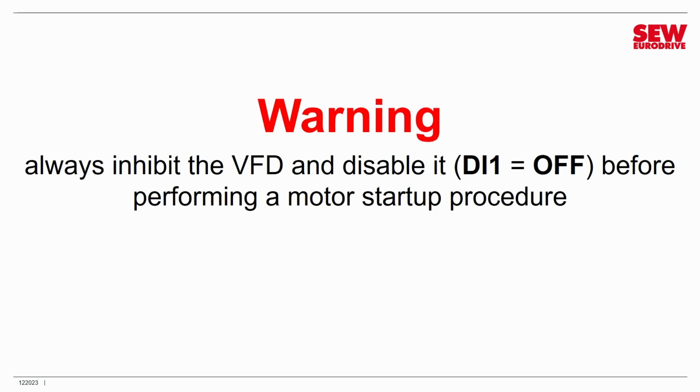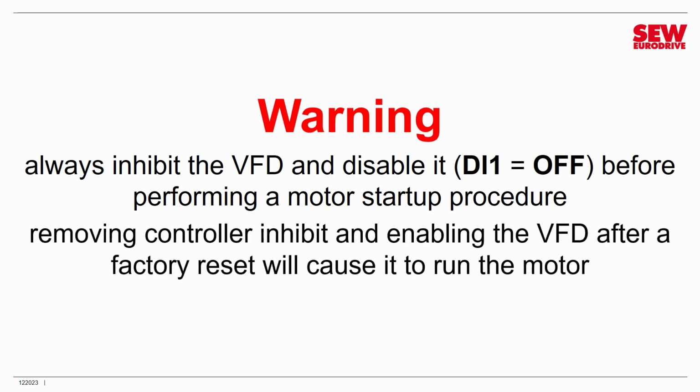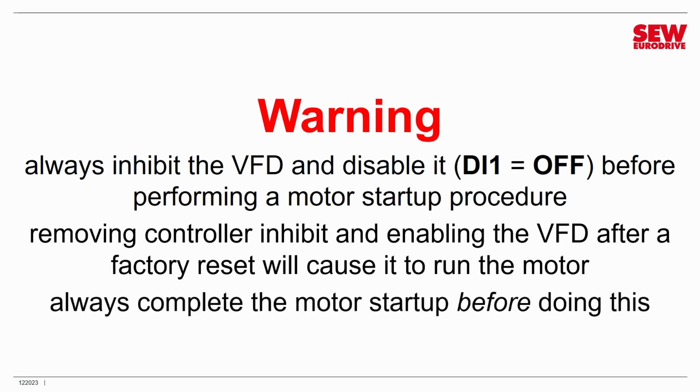We're going to be factory resetting our VFD, and it's a very good idea to do this because if you don't disable the VFD, the motor can start up immediately after a factory reset. You should always disable it and go through the complete motor startup before removing controller inhibit and enabling your motor. So remember, you have been warned.